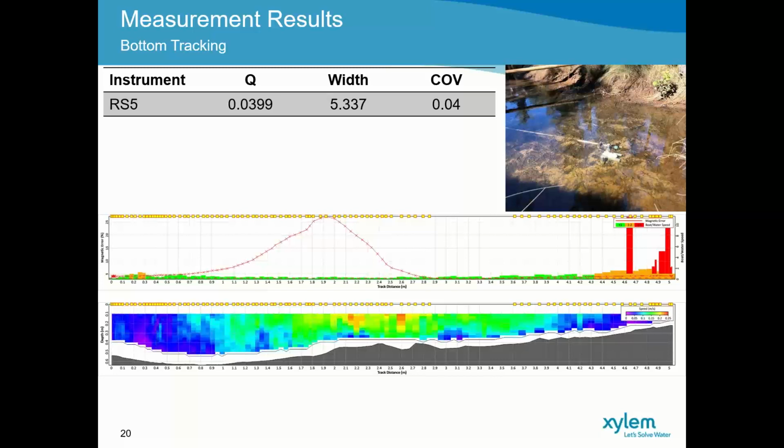Based on that, we can calculate the percentage difference between the compass calibration and the measurement as you perform it. In this case, we plotted the influence of the steel pipe, and there's a steel structure there where the IQ is mounted. So this whole trend here is based on that influence, similar to what the River Surveyor Live and River Surveyor M9 have.